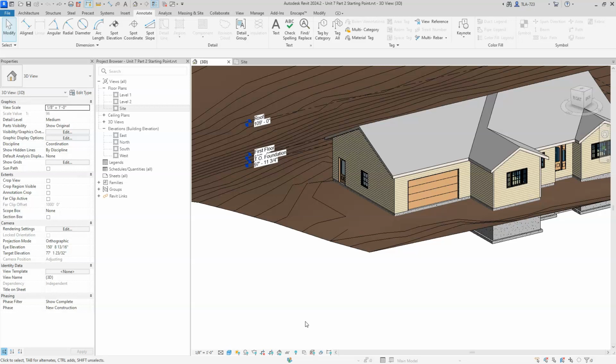In the situation where you're working on both, it is okay to have the topo in the same project as the house. It's just that keeping them separate sometimes makes more sense because it prevents you from changing that topography if you're working on the house and vice versa accidentally. Now we can also pin things. There's also constraints we can put on things to sort of overcome that. But working with links and or inserts is an important skill to have because it's done pretty frequently in industry.